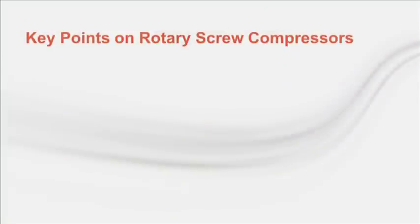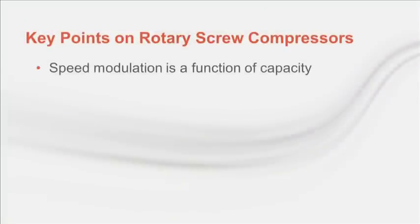True. How about if I summarize what we've gone through? Since rotary compressor speed reduction is a function of capacity, variable speed rotary chillers can make sense in hot and humid climates, even on applications where all variable speed drives in a plant with centrifugal chillers would not have been justified, since there may not be many hours with lift reduction in hot and humid climates.